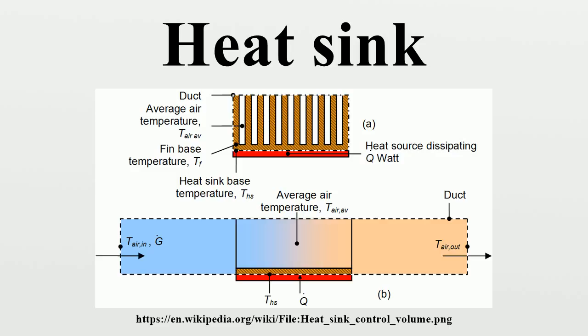In this case, finned heat sinks operating in either natural convection or forced flow will not be affected significantly by surface emissivity. In situations where convection is low, such as a flat non-fin panel with low airflow, radiative cooling can be a significant factor. Here the surface properties may be an important design factor. Matte black surfaces will radiate much more efficiently than shiny bare metal. A shiny metal surface has low emissivity.